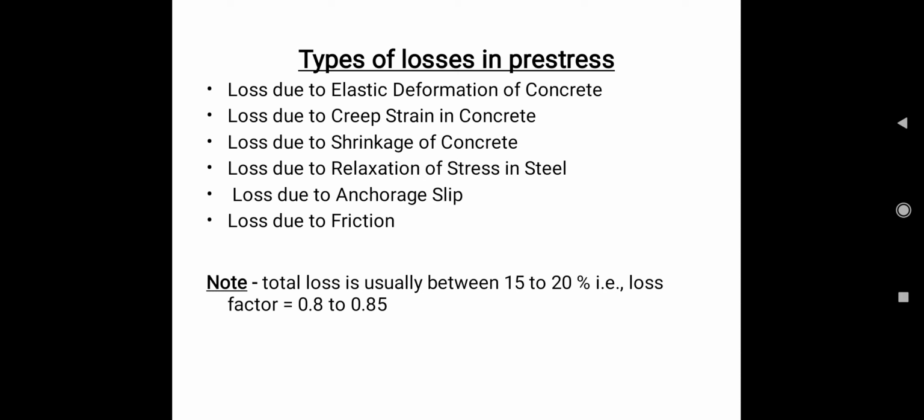Here we should keep in mind one thing, that is the total loss. The total loss which occurs from all these losses should be between 15 to 20%. If it is more than 20%, then the member is not suitable for construction.